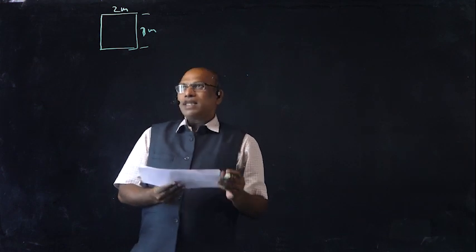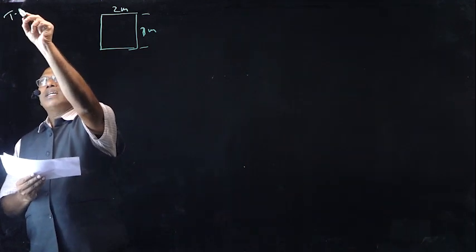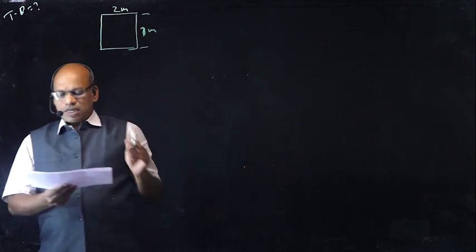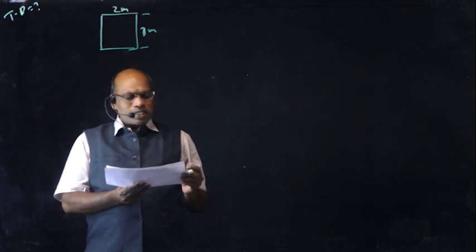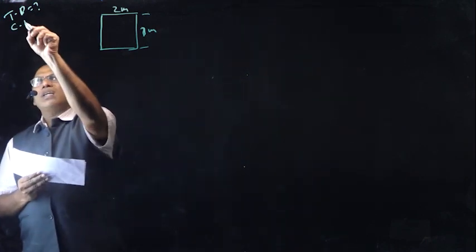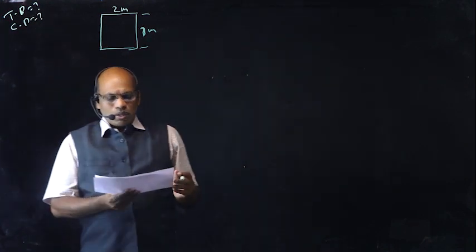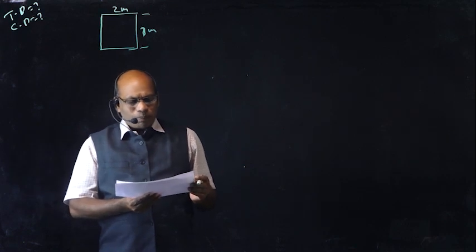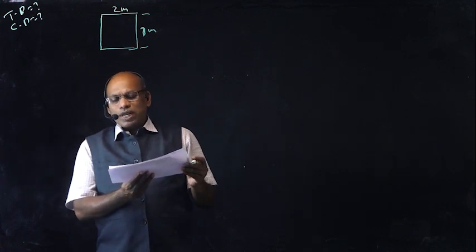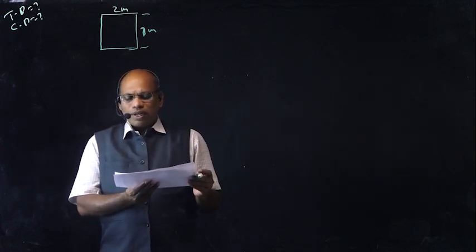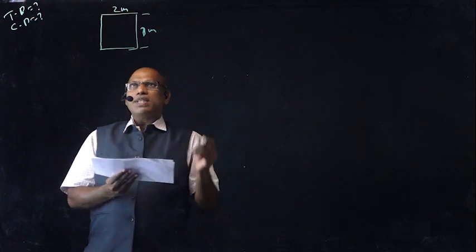Determine the total pressure, and the position of center of pressure on the plane surface when its upper edge is horizontal and one coincides with the water surface.